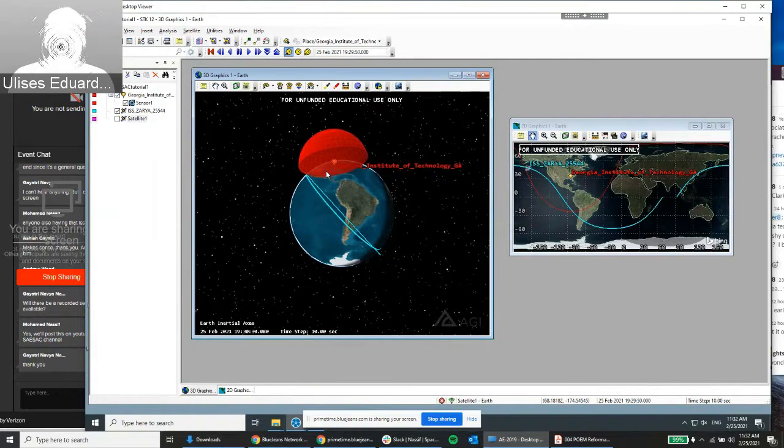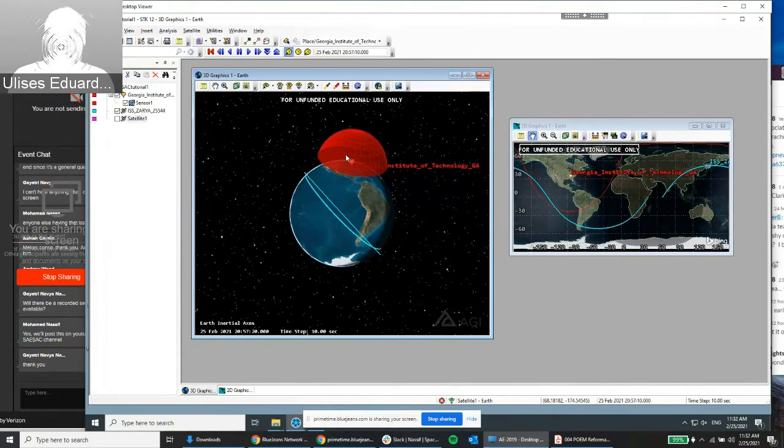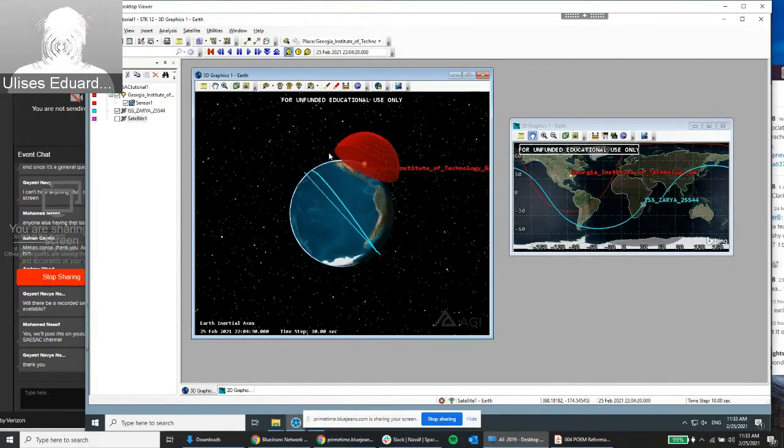Something that you can learn pretty easily from this is that in low Earth orbit, in the kinds of orbits that you get from CubeSats that you deploy from the International Space Station, with a sensor like this, you're only able to access them for about 5 to 10 minutes, 3 times a day, every day. So you do not have continuous access to a satellite in low Earth orbit unless you have a worldwide network of sensors. Again, that has a lot of implications that you can immediately visualize for your mission operations concept. Does that make sense?